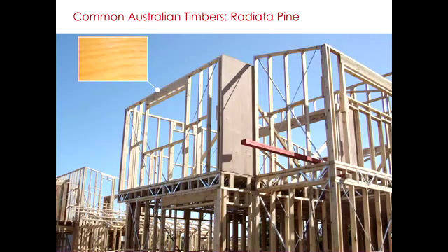Here you go. So this is radiata pine that is, for instance, used to make lintels, all right? The lintel is that beam that is used when you open a window into a stud wall, and therefore you generate a discontinuity in the structure of the wall. The lintel is able to carry the load from the upper floor and transfer it to the jamb studs. So that's the purpose of the lintel, which is made of radiata pine.